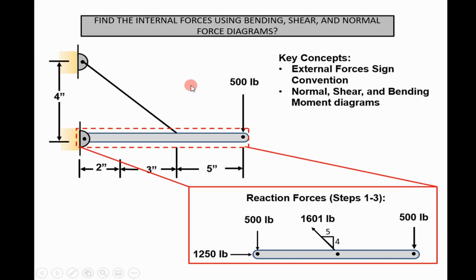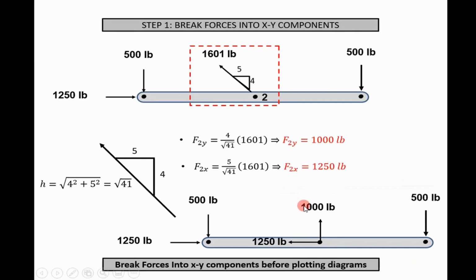Some key concepts I want you to focus on are the external forces sign convention, which is a little bit different than the internal forces, and then we're also going to cover normal, shear, and bending moment diagrams. All I'm going to do is add 2 steps onto this problem. Step 1, you want to break the forces into XY components. That's the first thing that you do.